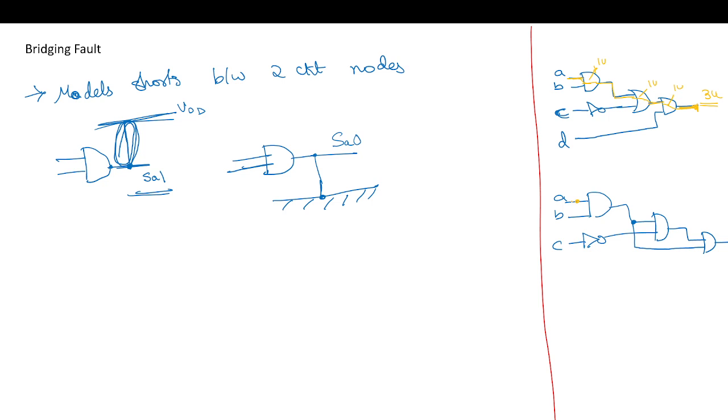So if the output could have propagated from this path, it would have seen 2 gates, and if it is propagated from this path, it would have seen 3 gates. So this is for the critical path concept. So I'm just coming to our node delay.